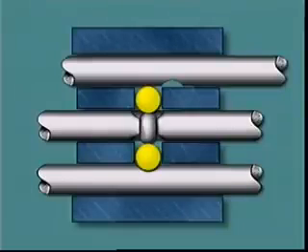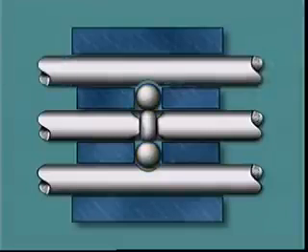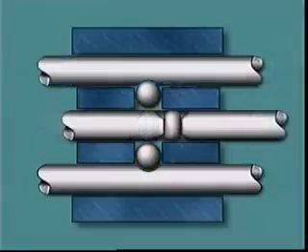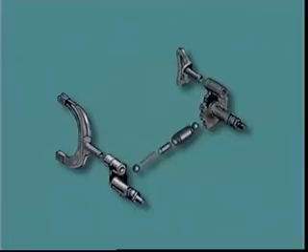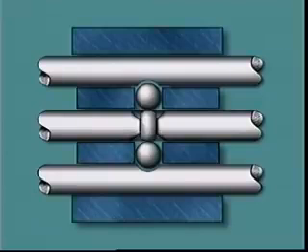The 2 balls held in the casing prevent movement of the interlocked rails and hold them in the neutral position. When the center rail is moved, the balls move into the grooves of the outside rails and hold them in a similar manner. All gearboxes are fitted with interlock and detent mechanisms, although designs vary according to manufacturer.